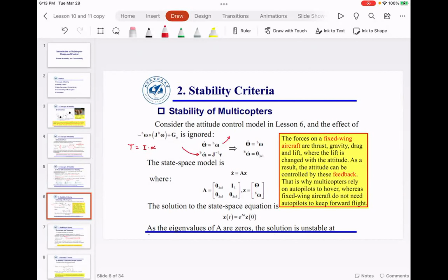But that is possible. Imagine the aircraft is pitching down. You increase the speed, but it may not go to the level flight. It can go up. And then you want to decrease the speed, so it will go down. So you would observe some sort of pendulum type motion in this dynamics. Same thing, you'll see the roll type motion, sort of a pendulum type motion in the dynamics. But once you add the derivative control, once you add the integral control, what essentially you are doing is you are converting. This is super duper important, so please pay attention.